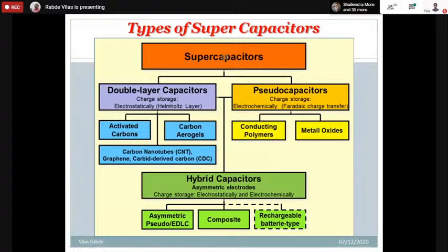Of course, some of these technologies will die once a better technology is available. Till date, a supercapacitor is not available above 2.5 volt, 2.8 volt to be precise, and that's why you have to use series-parallel combinations. Technology is growing, and very shortly supercapacitors with 48 volt or 100 volt will also be available.